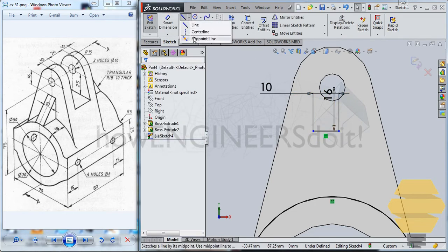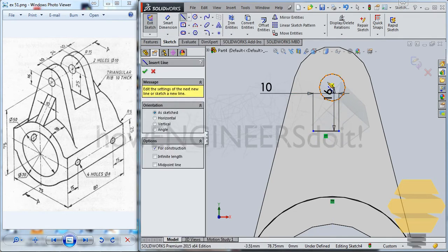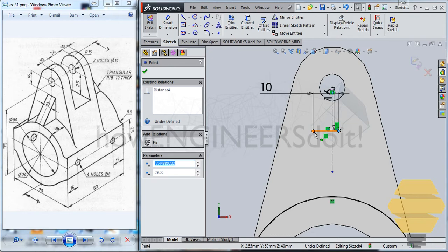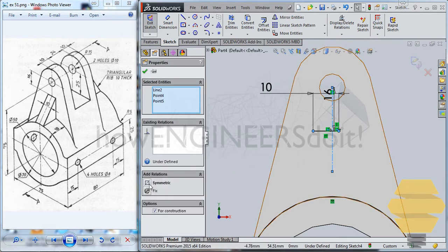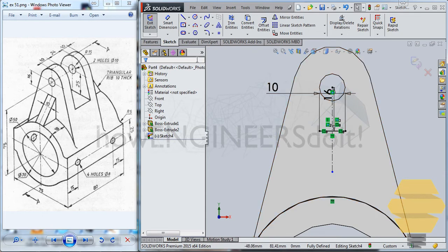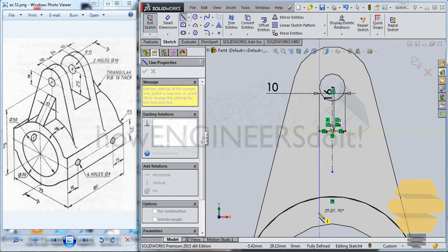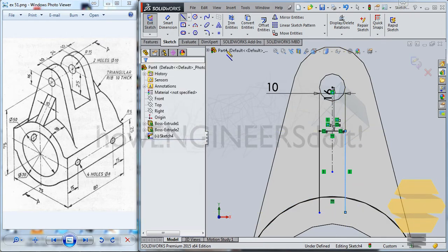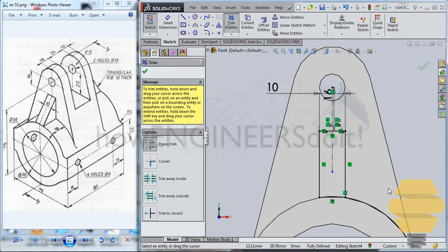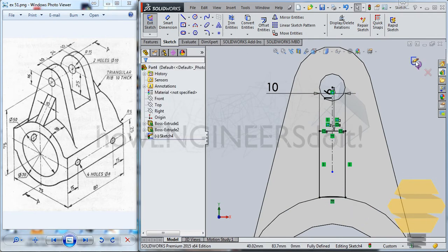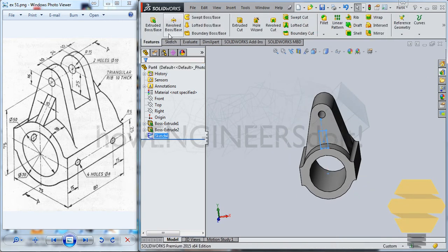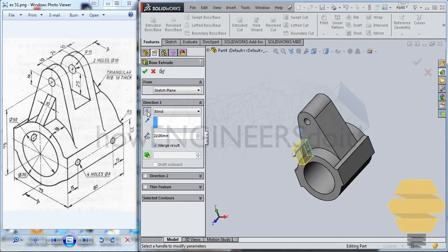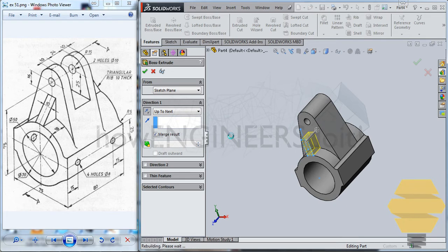and you can draw an axis line here and select 1 and 2 and this axis line and go for symmetry, tick mark, and also draw a line downwards and another line downwards, and use the trim command to trim all these portions off. Tick mark and exit sketch, and now you can simply use the extrude reverse direction, up to next will do the trick. Double enter.